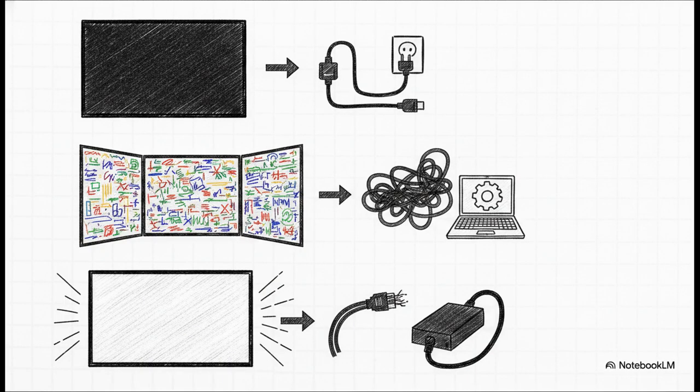If the entire screen is all black, you check the mains power, you ensure you actually have a video signal, and you verify if the sending card itself has failed. If the image is disordered and fragmented across multiple cabinets, well, your physical cable routing probably doesn't match your software connection settings. And if the entire massive display is flickering, look, that is rarely a dead pixel. It points to poor network cables or a major voltage drop. The solution there is to reseat your main cables or just replace the main power supplies providing the voltage.